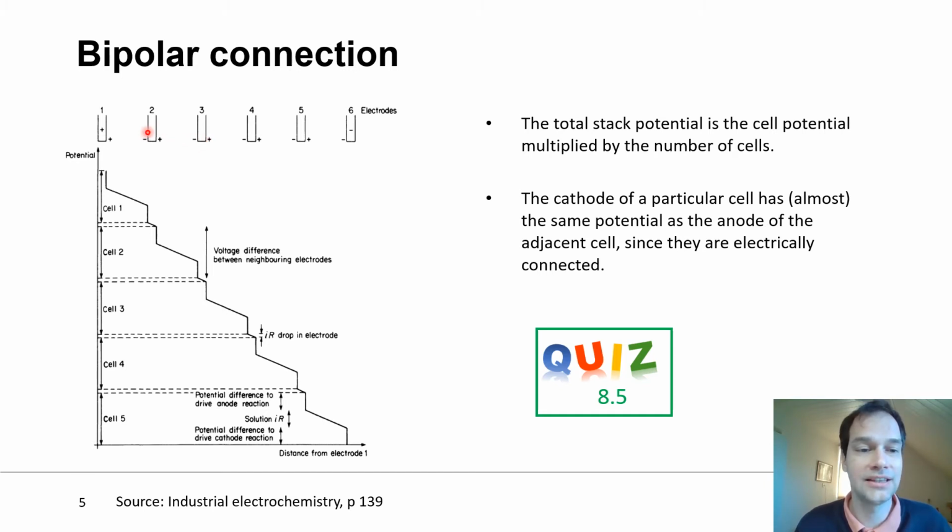What you can say is that the potential difference over the electrode is very small because it's a metal. So it is actually 8 volts on both sides. It could be 0.01 volt difference, but a very small number. And so you can continue. This was 10, 8, 6, 4, 2, 0, and you continuously have these steps of 2 volts. And this forms the total stack.